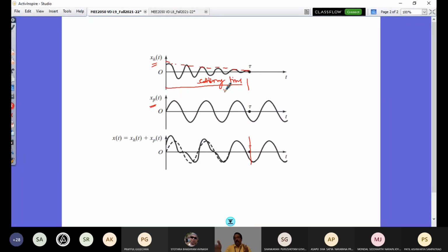When I see my vehicle from the top view, it should not vibrate like that with respect to the vertical axis. That effect would be taken care of by the damping present in our suspension. That's the role of suspension. This is all from a vehicle dynamics perspective. We are going to look at it in detail in the vertical dynamics part, and this fundamental of forced vibration is important for you. That's why we are learning it in this first module. I hope you have understood this.